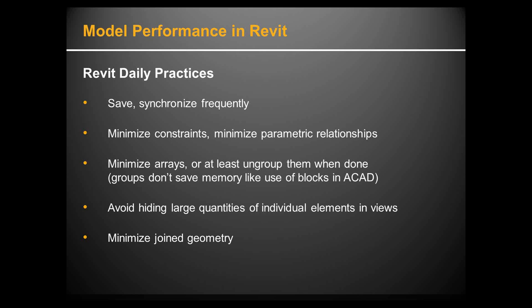Yeah, like a lot of these things, there's reasons to use it and there's reasons to not use it, and the hard part is knowing when to do which. Avoid hiding large quantities of individual elements. If I had time, I would do that in Revit. So if you click on one element, say I don't want to see this furniture group, or maybe I have an enlarged view and so I want to hide them in the floor plan and only show them in the enlarged view, I would use Worksets for that.